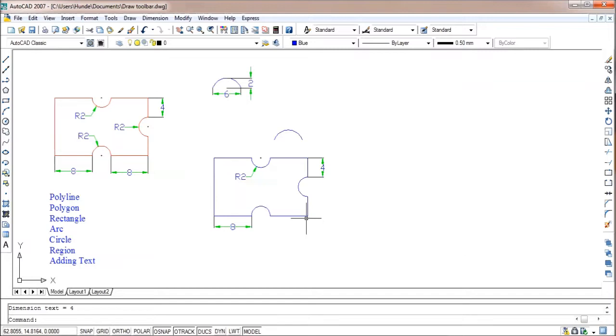So we get the perfect object which is given for us using polyline. The main purpose of using polyline is to draw objects having both line and arcs by switching between the two commands. Okay, so the next command, let us draw rectangle command.